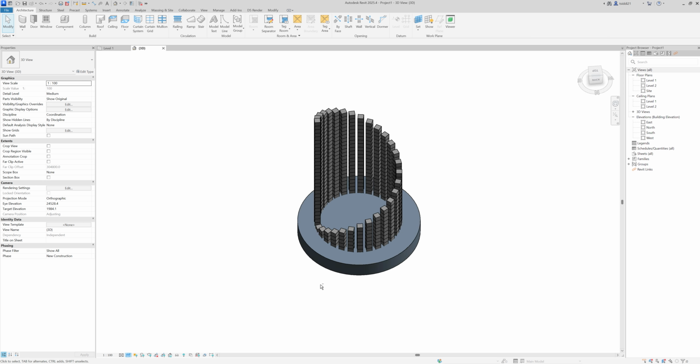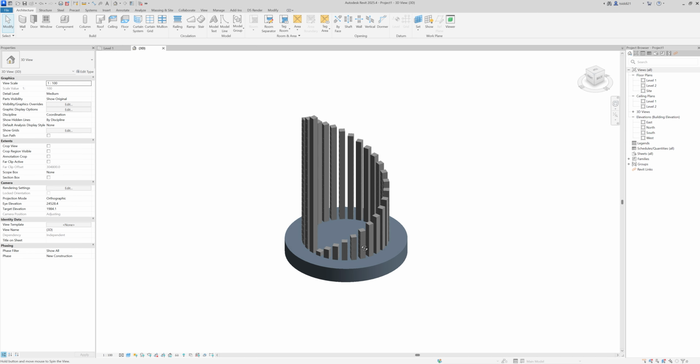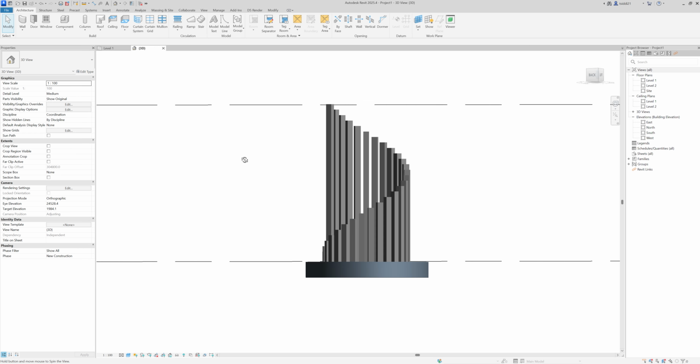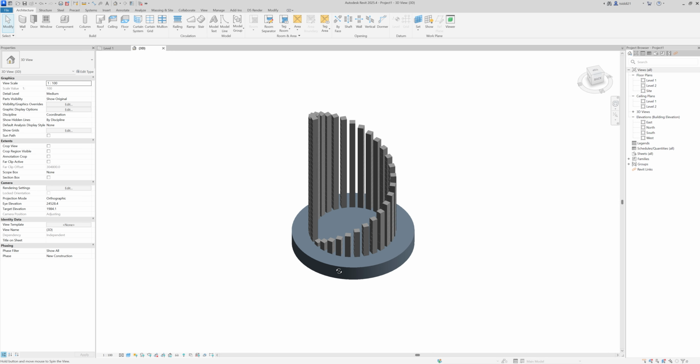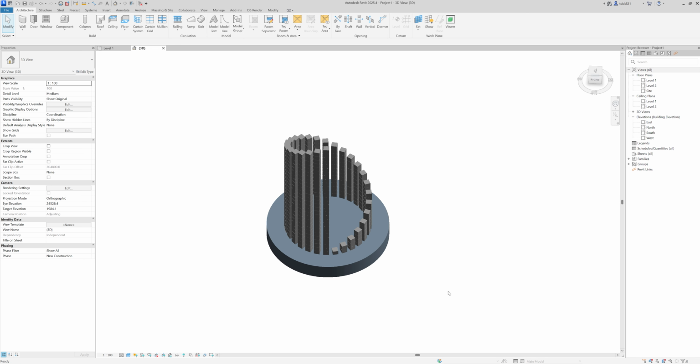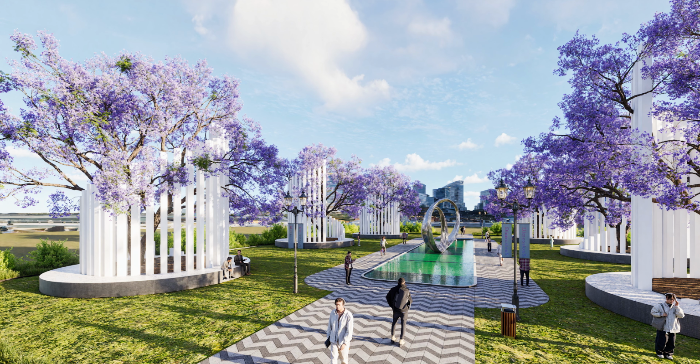That's the complete workflow, starting from a simple circle in Dynamo, distributing coordinate systems along it, placing cuboids at the coordinates, using curve length and sliders to control the spacing and height, translating the geometry into a vertical shell, and finally grounding the design with a Revit floor. You can adapt this setup to create different kinds of parametric towers, facades, or atrium walls, just by changing a few values and formulas in the graph.